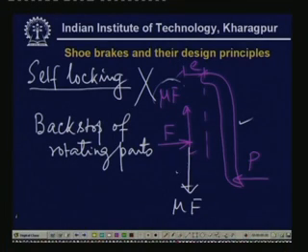So, this can be taken care of in a backstop of rotating part. So, what we must have is P as small as possible. Therefore, we need to consider this offset. If the offset is 0, then P is taken directly by the lever principle, that is P times L will be F times A. But if the offset is chosen properly, then even a larger mechanical advantage could be used, and if the mechanical advantage is gained, then we call this the self-energizing action of the brake. So, we need a self-energizing brake, but at the same time we want to avoid self-locking of the brake.